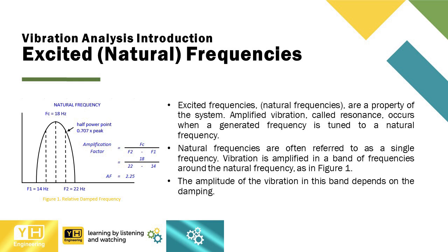Vibration Analysis Introduction. Excited frequencies, natural frequencies, are a property of the system. Amplified vibration, called resonance, occurs when a generated frequency is tuned to a natural frequency. Natural frequencies are often referred to as a single frequency. Vibration is amplified in a band of frequencies around the natural frequency, as in Figure 1. The amplitude of the vibration in this band depends on the damping.